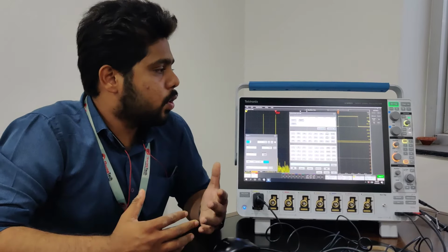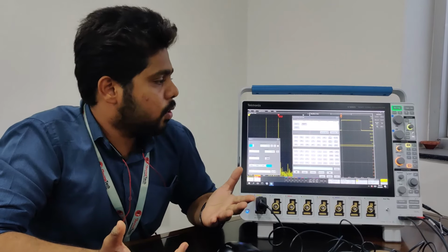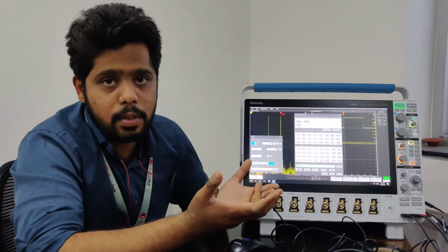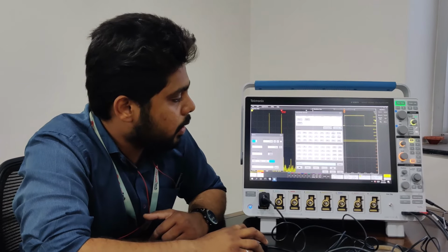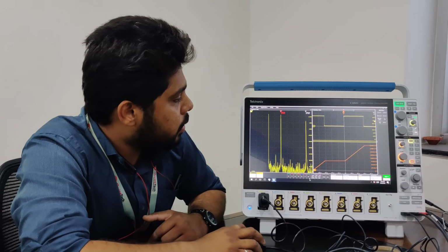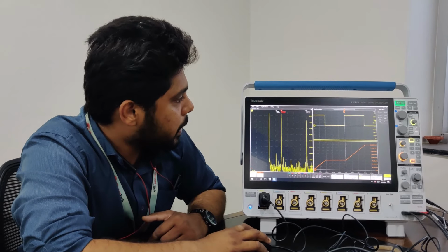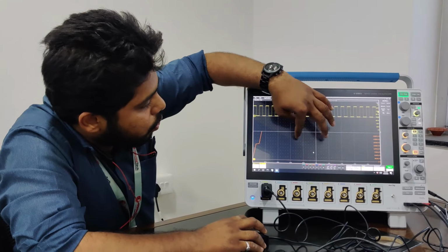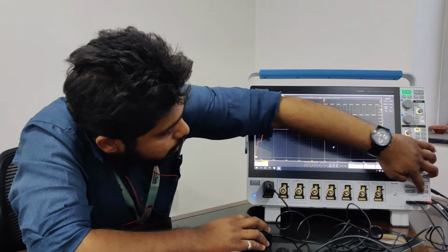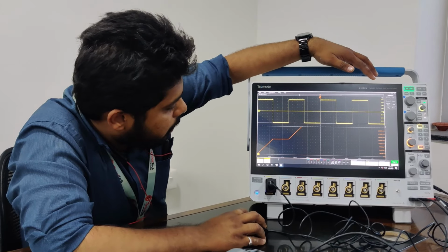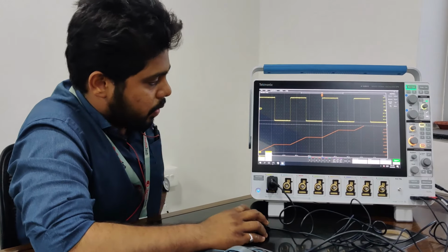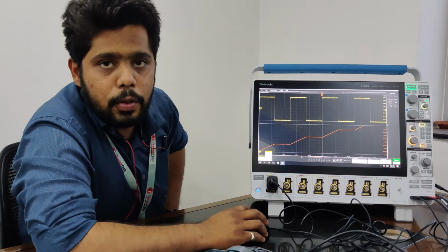Okay, so let's take an example. I don't know how the integration of a square wave looks, so I'll take the integration of channel 1. Channel 1 is a square waveform. I'll complete the bracket and click OK. As you can see over here, I'll close the spectrum part. Yeah, so you can see at this part, right? This is how the integration of a square wave looks.